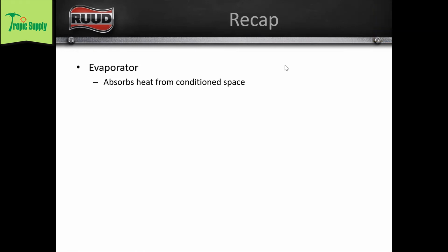Yeah, we do. And then the other one was, for instance, in a hot attic, with the expansion valve mounted on the outside, wouldn't it be more beneficial to mount it on the inside? My answer is, if it's insulated with the copper, that hot attic shouldn't be an issue, correct? Absolutely. It's crucial that it gets insulated. You can't really insulate it too much. I always used the insulation that came with it, and I'd also cut a couple pieces of Armaflex to add to that insulation, because you can't over insulate your valve really.